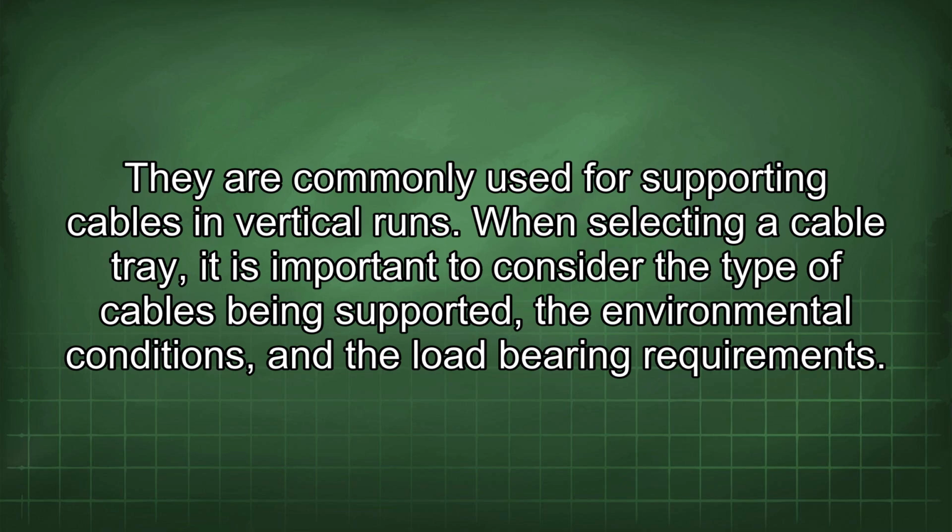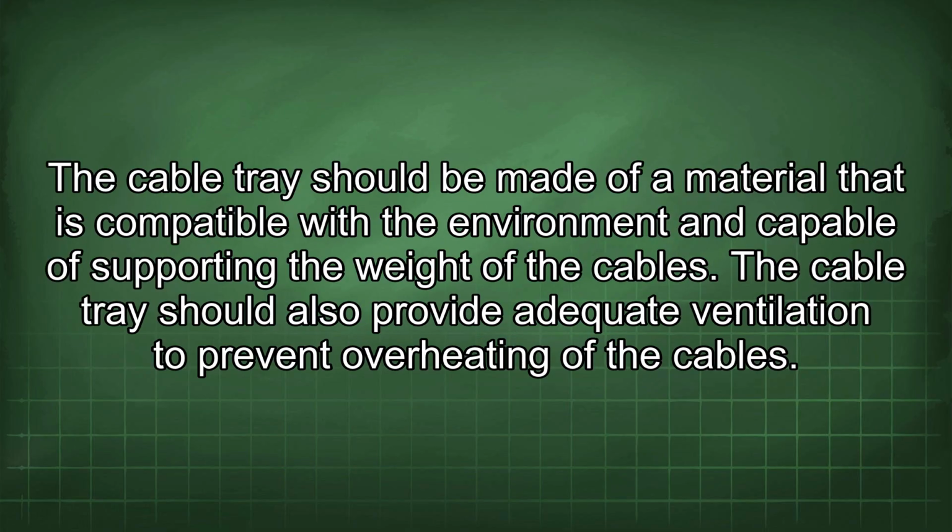When selecting a cable tray, it is important to consider the type of cables being supported, the environmental conditions, and the load-bearing requirements. The cable tray should be made of a material that is compatible with the environment and capable of supporting the weight of the cables. The cable tray should also provide adequate ventilation to prevent overheating of the cables.